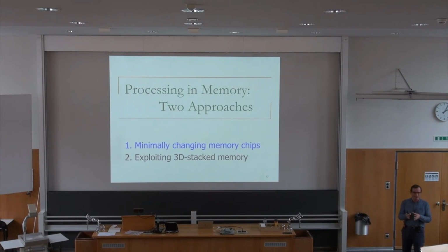Basically, if you actually take a full CPU, for example, if you want to put it inside the memory chip, that's not an easy thing to do, because if you want a really high performance CPU, you really want a process that's customized for high performance. And the memory process is really not customized today for high performance. It's really customized for high capacity. How do you make that capacitor as little as possible, as less leaky as possible, as opposed to very high performance? And actually, whatever CPU you put over there is not going to be easy to make extremely high performance. Maybe you can put something very small over there.